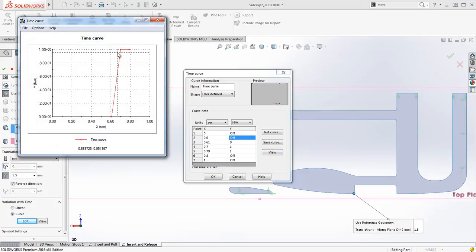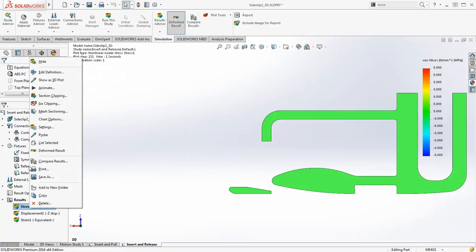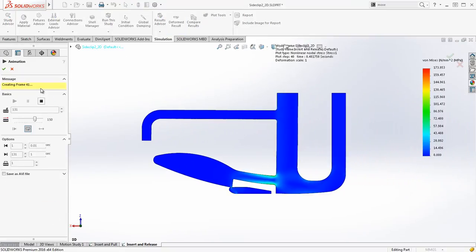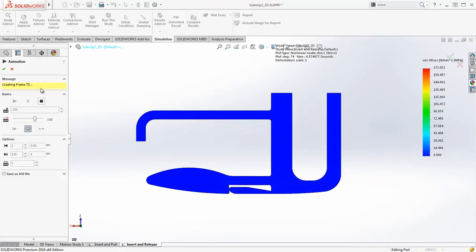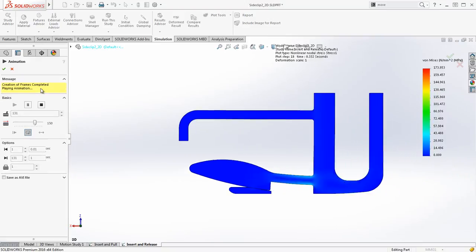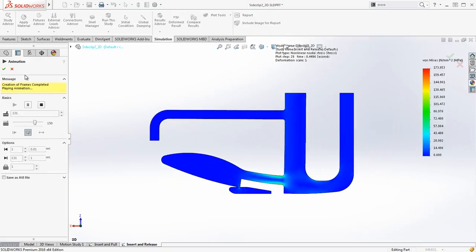The benefit of this sequencing is that the calculated loads are accurate for the entire operation and no artificial stresses are induced. You can then be confident in the resulting performance data and ensure it meets your design needs. In the animation, we can see the insertion, the side clip then being pressed in, and then finally the clip being pulled out, allowing us to confidently determine the forces needed for these operations and ensuring they meet our requirements.